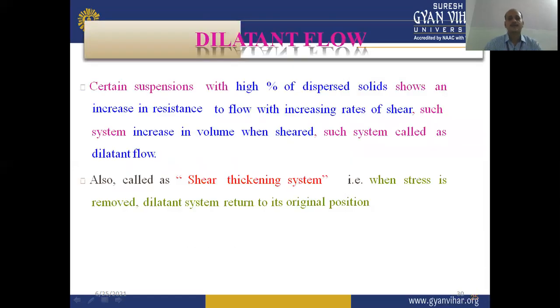So dilatant flow: certain suspensions with a high percentage of dispersed solid show an increase in resistance to flow with increasing rate of shear. Such systems increase in volume when sheared, and as per the mechanism of increase or expansion in volume, they are called dilatant flow.